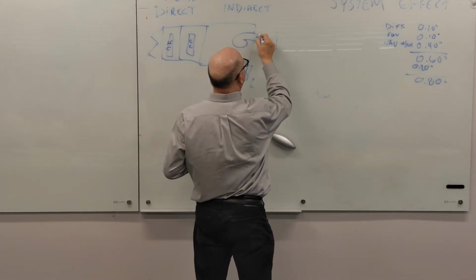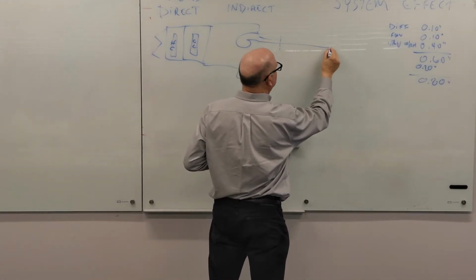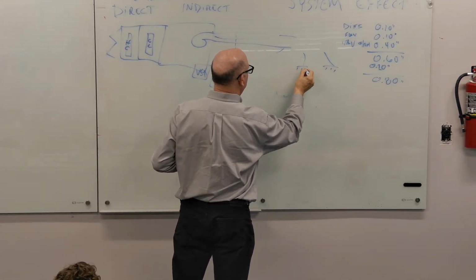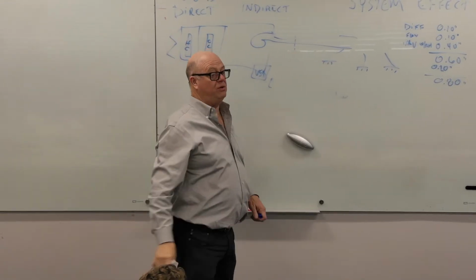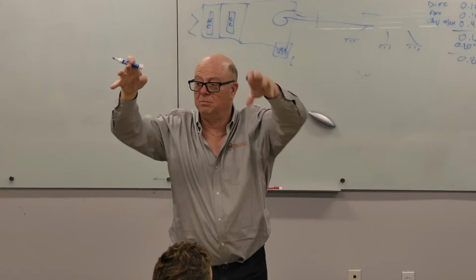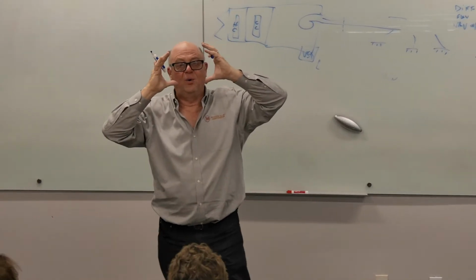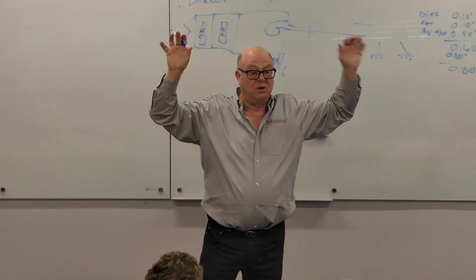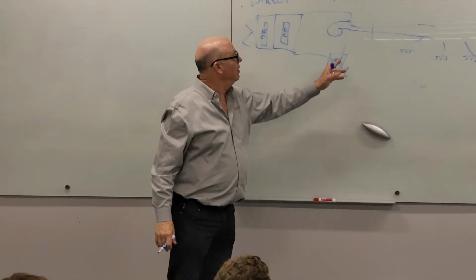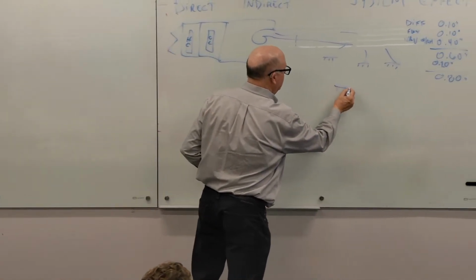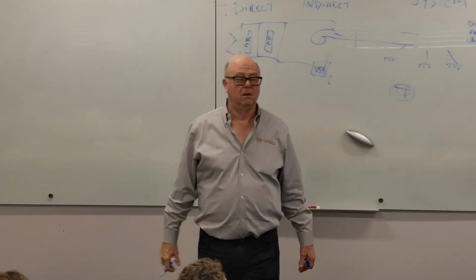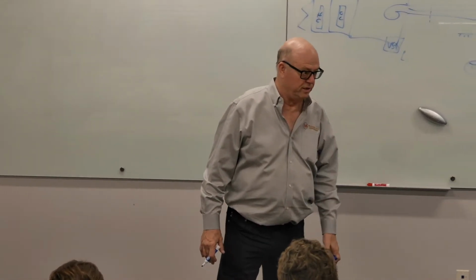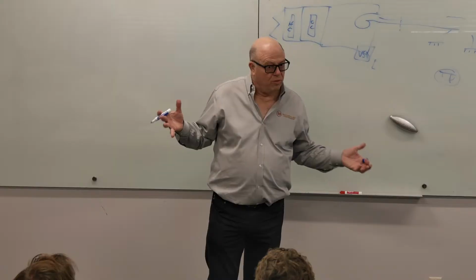And the duct comes out, and you're probably measuring the airflow, but the duct comes out and it branches in a couple of places, you know, with some diffusers for the barn. And maybe you don't even have that kind of diffuser. If it's a big barn, it's probably some kind of a horizontal blow thing, whether it's those round-outlet diffusers that turn around, or whether it's just horizontal grills set up. You've got one sensor out here, and you've got to think about where you want that to be. If you really insulate the barn wall on the sunny side, and I mean really insulate it, you might get away with a single zone.